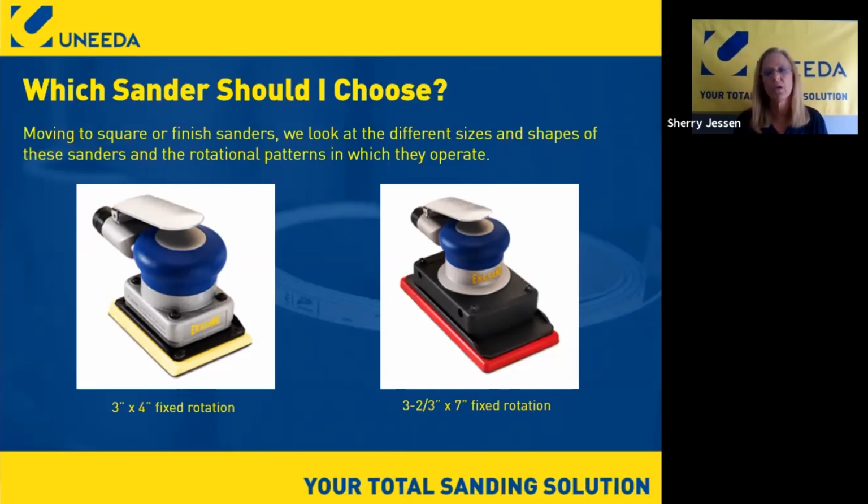We can reduce the swirls if we go to a pad saver, and I'll tell you, without the pad saver, you will hate the sander on raw wood, just because it tends to grab. As you start to sand across the surface, it will grab the wood and it'll skip. And when it starts to skip, it's hard to control. The pad saver works kind of as a shock absorber, so it allows it to move a little bit smoother across the wood. But honestly, I haven't really found anything that stops the swirls with the 3x4, unfortunately.